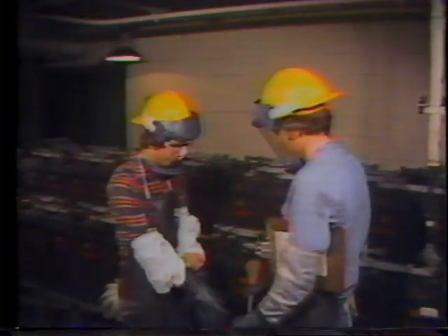You can see how specific gravity testing is done here. Notice the protective equipment. Anyone who makes a specific gravity test or does any other work on or around a battery should wear equipment that provides protection from contact with acid. The test is begun by discharging the air from the hydrometer and then putting the bottom part of the hydrometer into the cell. Atmospheric pressure will push a sample of the electrolyte up into the hydrometer.